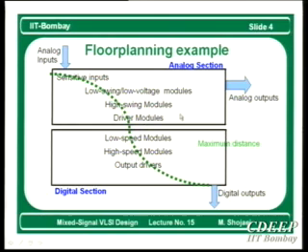So these are here. And then if you have analog outputs, you try to keep them separate, quite far from output drivers of the digital part. So therefore they are still far away from each other, but they may not be too far as compared to analog inputs and digital outputs. Then whatever low speed modules you have in your digital circuit, you keep them close to the analog section. Then you go with high speed modules and then finally with final drivers. Okay?